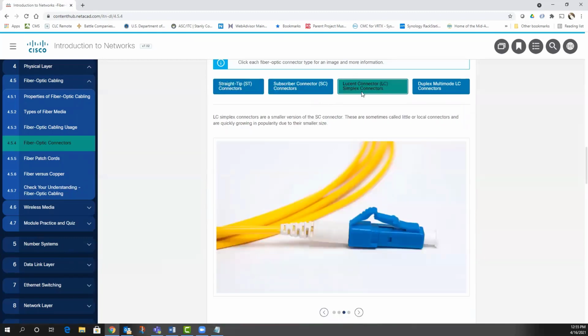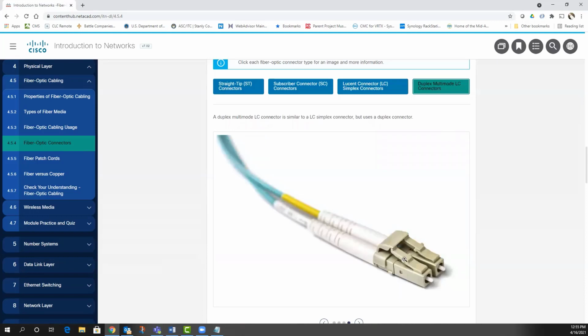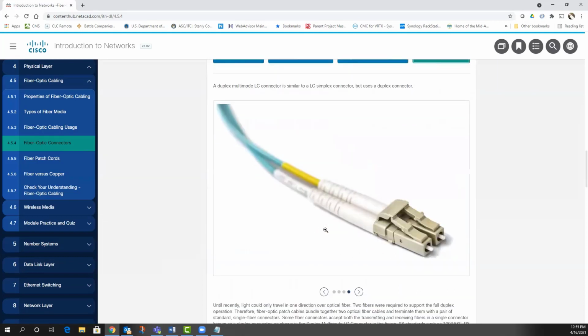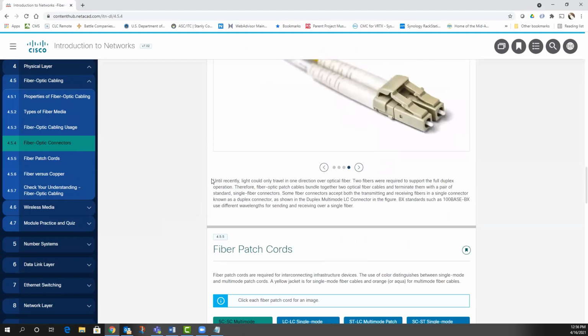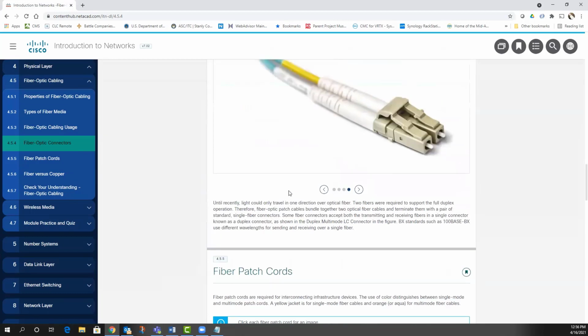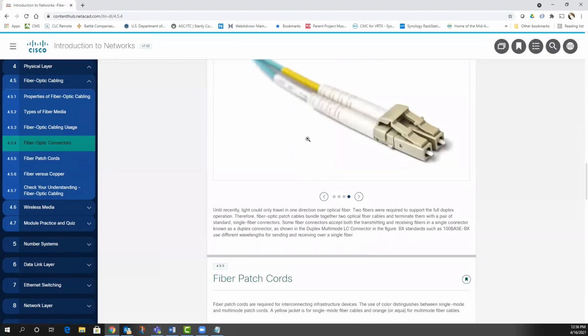We have these Lucent connectors, simplex. Okay, so singles that click, and then we have duplex mode LC connectors that actually mold the send and receive pair together, and you click them in. And that way they're already made to be send to receive on each side, so they're crossover basically. Now they're starting to work it now where you can do both, so you can actually send and receive on a single connector, but you'll still typically see these in pairs.